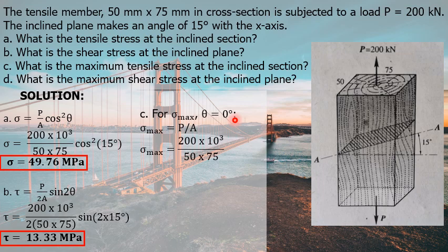Our P is 200 times 10 raised to 3, our A is 50 by 75. Our maximum tensile stress is equal to 53.33 megapascals.